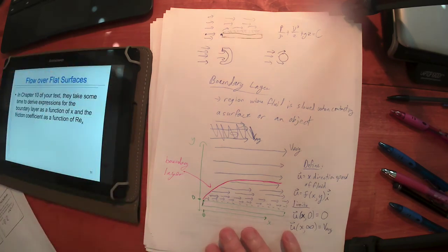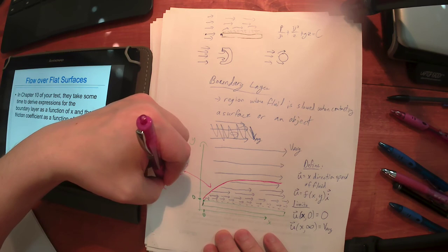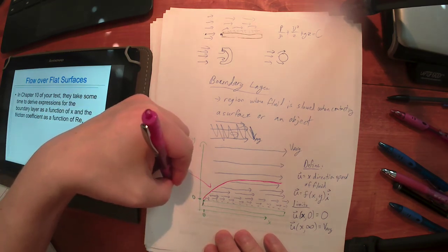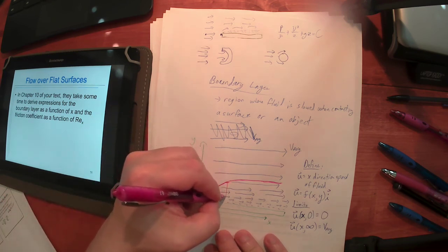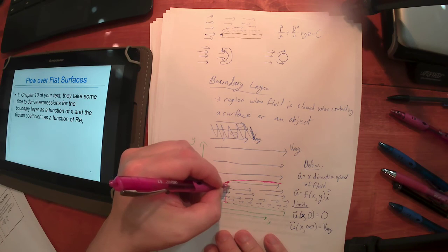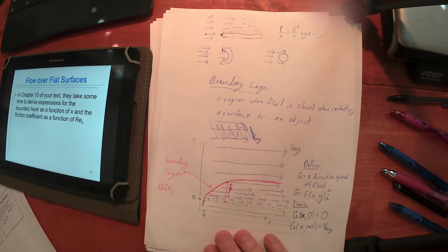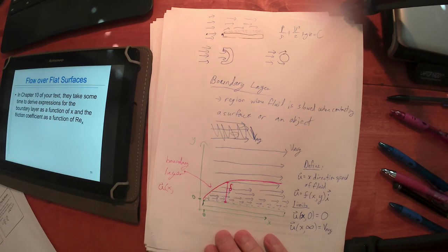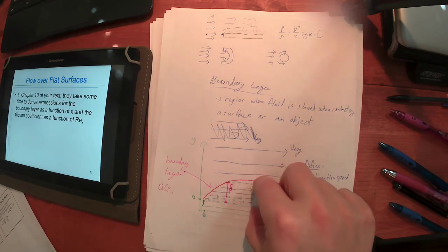The boundary layer is defined typically as where you get a u value at any x location, and a lot of times we'll use a value here, we'll just call it the del, kind of an inexact differential, d, and at least this text likes to use del to refer to the thickness of the boundary layer. So that del value is going to have different lengths at different x values.